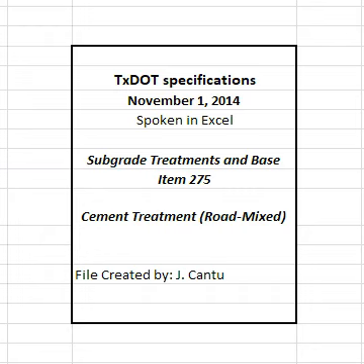2.3 Flexible base. Unless otherwise shown on the plans, furnish base material that meets the requirements of Item 247, flexible base, for the type and grade shown on the plans, before the addition of cement. 2.4 Water. Furnish water free of industrial waste and other objectionable material. 2.5 Asphalt. When permitted for curing purposes, furnish asphalt or emulsion that meets the requirements of Item 300, asphalts, oils, and emulsions, as shown on the plans or directed.